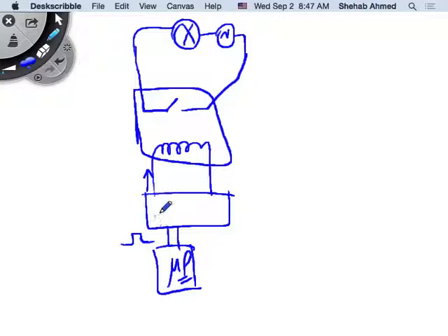And then you'd have an amplifier circuit like you studied in 325 that would take your 5 volts with no current at all and amplify that, right? Maybe a voltage follower, for example, right? Simple circuit like that. And then this will drive the relay coil, and the relay coil will drive the mechanical contact, right? So it's a very nice simple circuit, and it will impress lots of people very quickly.